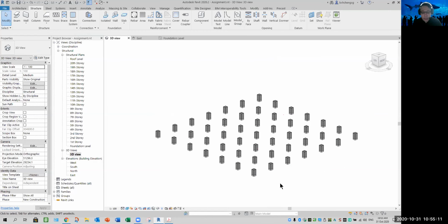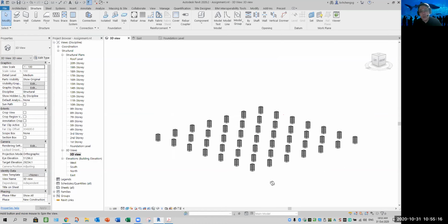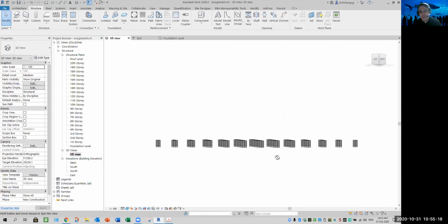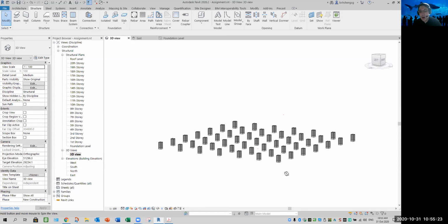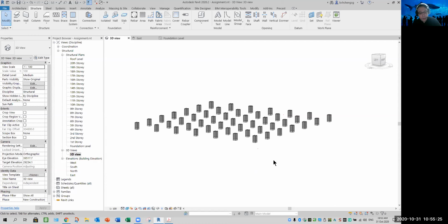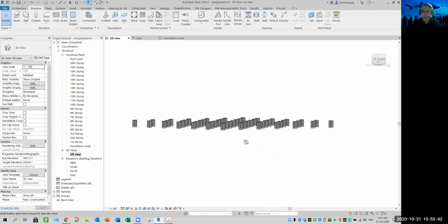The second method of adjustment will be what? You adjust the view this way, using your mouse. Now, how do I do this? This is what I call free orbiting: you press the shift key and depress your scroll wheel, the middle button, press it and drag.